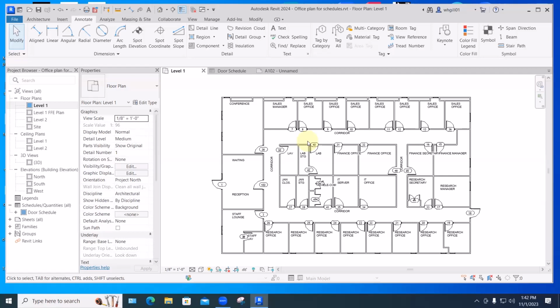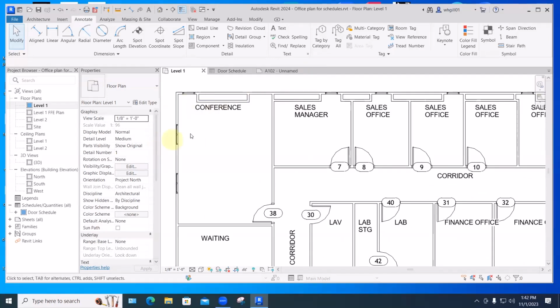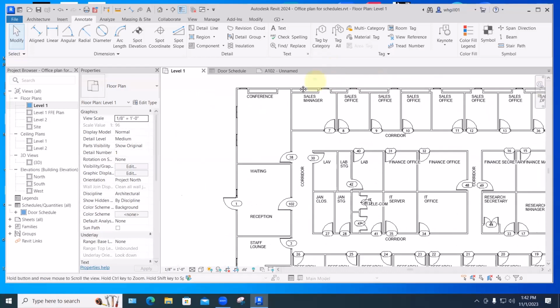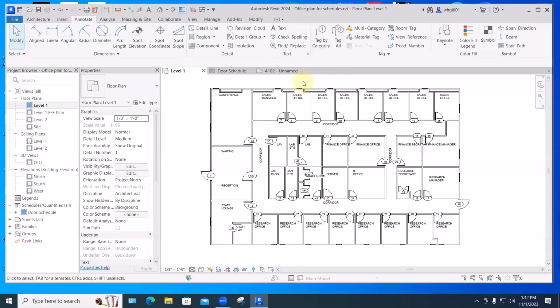Windows, on the other hand, I think here in this building, there are just 2 or 3 different types of windows. So instead of saying window 1, window 2, window 3, window 4, window 5, window 6, we just want to see that this might be window type A, this might be window type B, this is a B, this is a B, this is a B. And that really lets whoever's doing the quantity takeoffs realize, oh, I got 16 Bs and 7 As and I'm good to go. They come in on a truck, just plug into a hole in the wall.